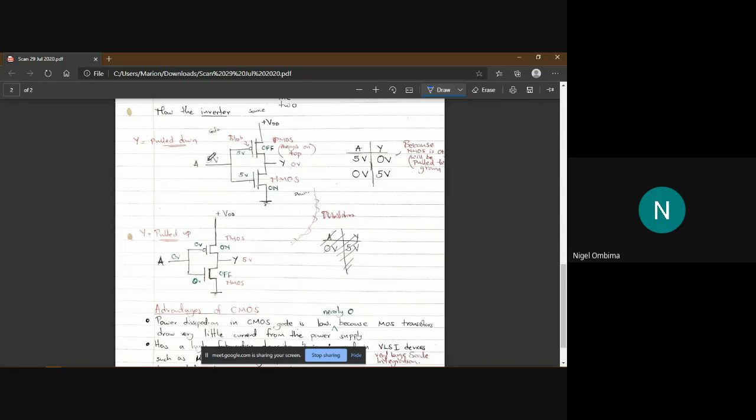So when you connect 5 volts, it reads 5, it's a high. And then the NMOS is on, but remember, since NMOS is a dual of PMOS, if NMOS is on, the PMOS is off. So this output Y can't get voltage from over here.